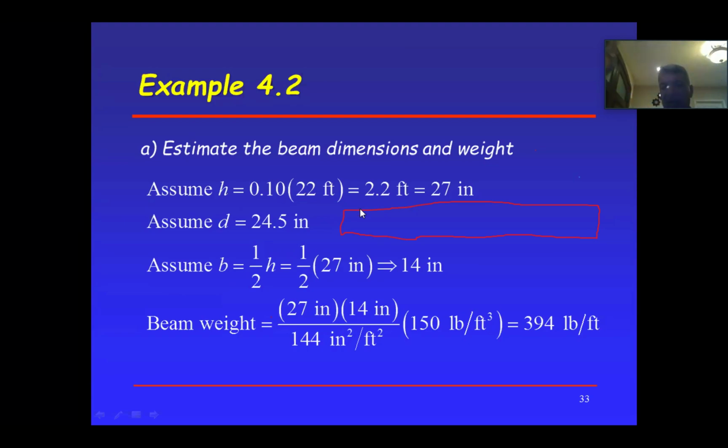That's how W is a uniform load along the beam. So if I calculate it as length times depth times width in pounds, then I have to go back and divide by the length to make sure it's along the beam. So instead of doing that, all I do is multiply by the depth and the width, and then don't multiply by the length, and then you get the answer in pound per foot.